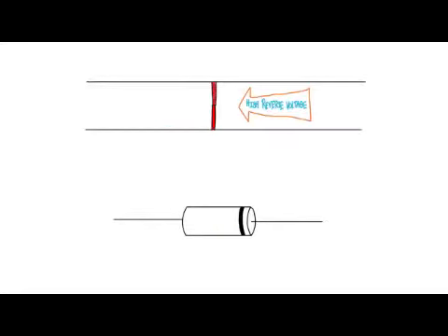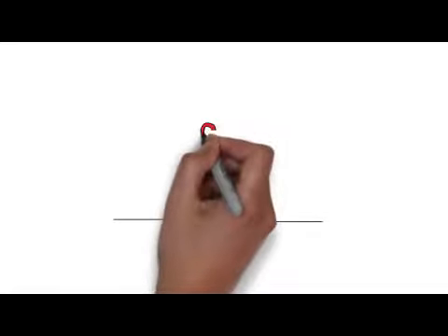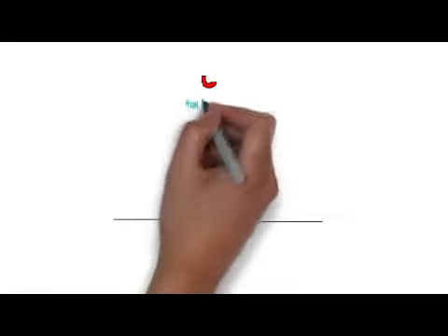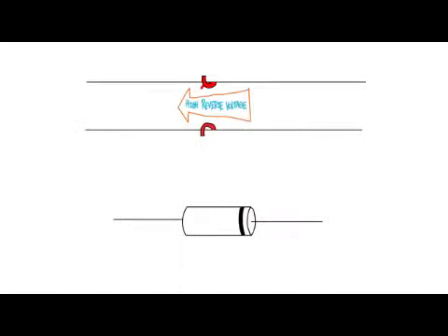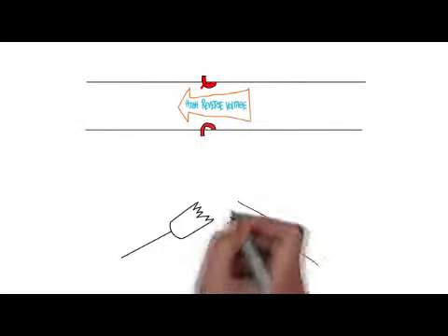Anyway, the ability of a diode to withstand reverse bias is limited. If the applied reverse bias voltage is large enough, the diode will break down. And when that happens, there's a good chance the diode is damaged.